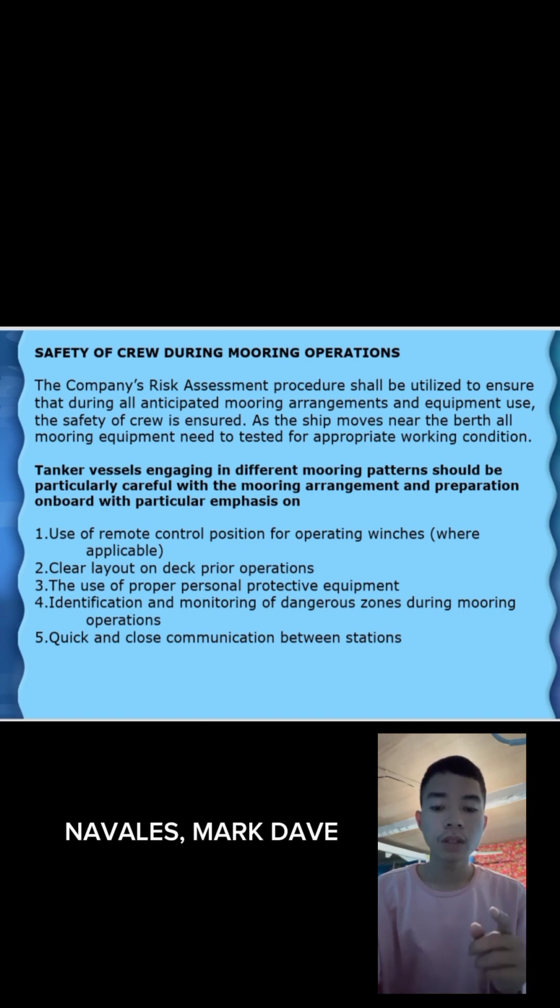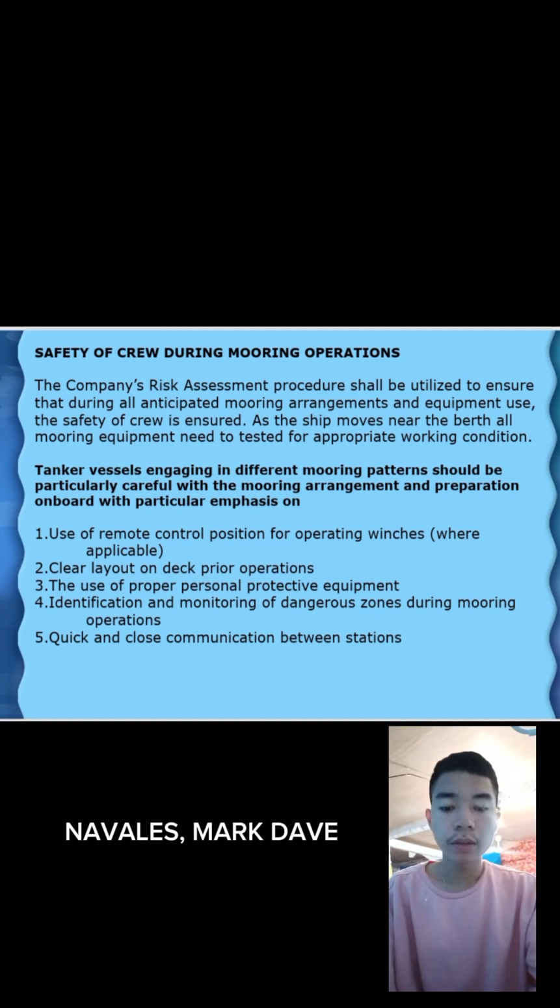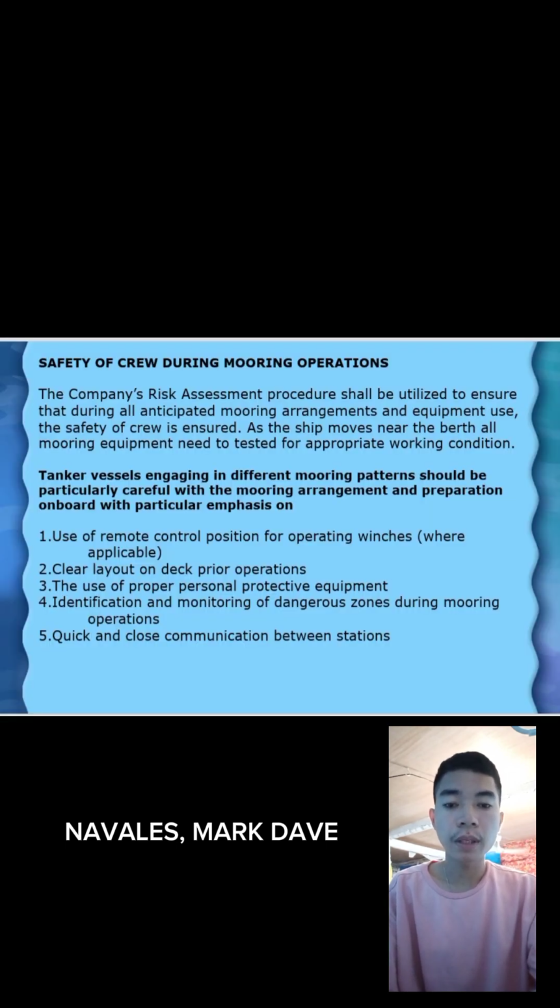Number 1, use a remote control position for operating winches where applicable. Number 2, clear layout on deck prior to operations. Number 3, the use of proper protective equipment. Number 4, identification and monitoring of dangerous zones in mooring operations. Number 5, quick and close communication between stations.